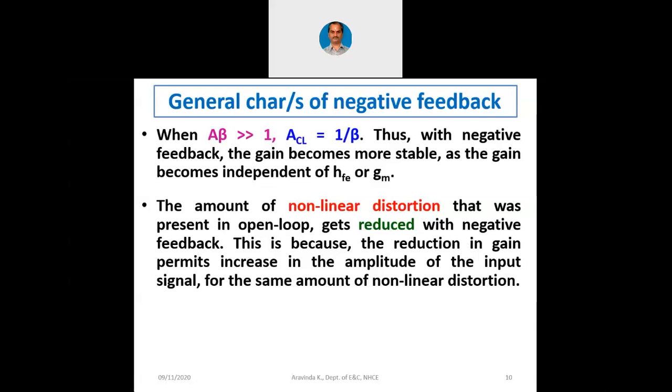For example, let us say the input signal is 1 volt and let us say the gain is 10 times of an amplifier and let us say the supply voltage to the amplifier itself is 10 volts. So now gain is 10 times, input is 1 volt, supply voltage is 10 volts. Means the transistor would be operating in the quiescent point where transistor would be exactly at 5 volts when the circuit is switched on. Now when the input signal is given 1 volt, now it is 10 times, so we can get an output of 10 volts peak to peak.